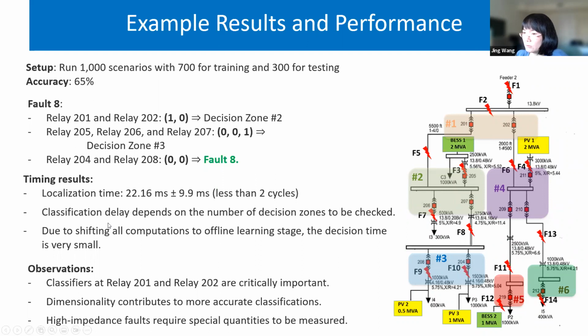With all the tests we run, we have this time to locate the fault, and you can see it's actually quite fast. It's less than 2 cycles with all sorts of scenarios we run. We connected as islanded, high and low impedance, different fault locations, different solar and load irradiation profiles, and the PV operation modes as well. So it is a very comprehensive test.